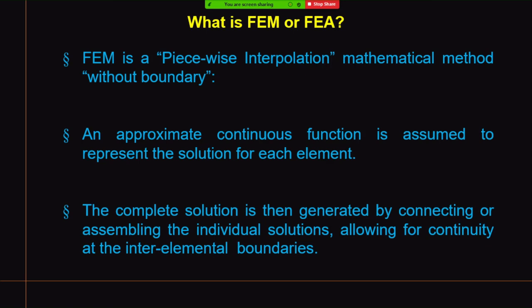I want to solve it. Solving the beam means I am going to apply a force here, and this is x equal to 0 and this is x equal to L, and ultimately you want to determine the deformation pattern like this, so I need y equal to some function of x. This is the solution you are looking for.